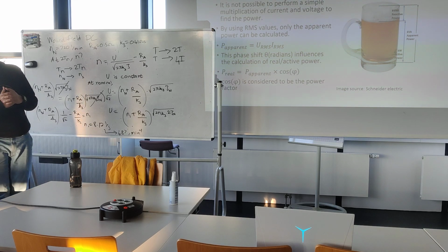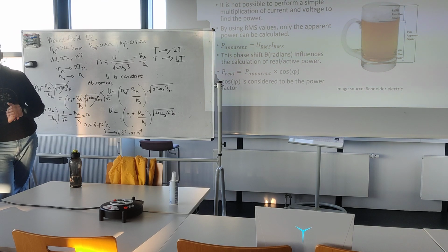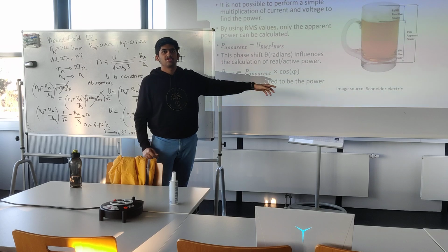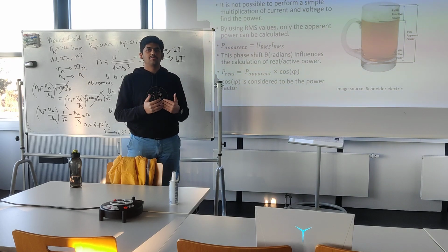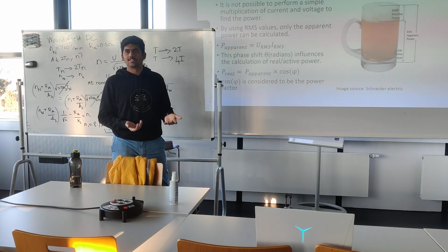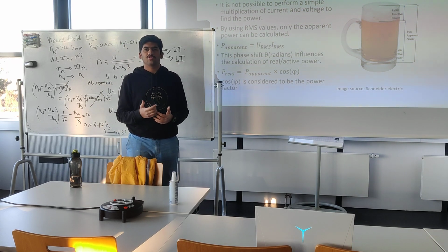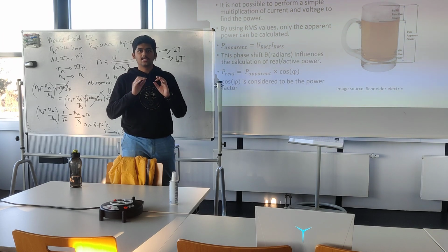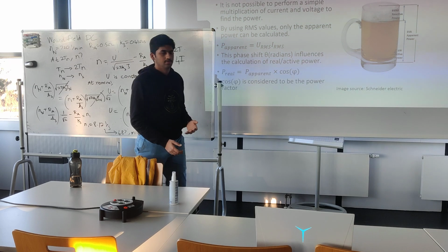And for the ideal case where we want to utilize the given wire to the maximum extent possible, we try to have a high power factor, because when you have a high power factor, you are giving as much power as possible, and the maximum it can be is 1, because cos theta max is 1. When you have a power factor of 1, it means voltage and current are perfectly in phase, and the current that you are carrying is absolutely useful to do work.